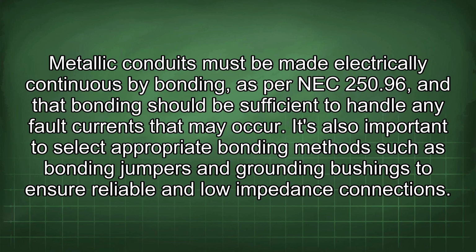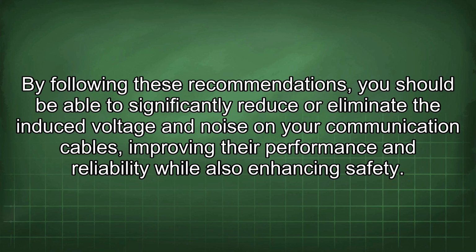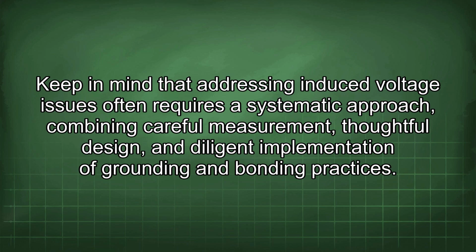It's also important to select appropriate bonding methods such as bonding jumpers and grounding bushings to ensure reliable and low impedance connections. By following these recommendations, you should be able to significantly reduce or eliminate the induced voltage and noise on your communication cables, improving the performance and reliability while also enhancing safety. Keep in mind that addressing induced voltage issues often requires a systematic approach, combining careful measurement, thoughtful design, and diligent implementation of grounding and bonding practices.